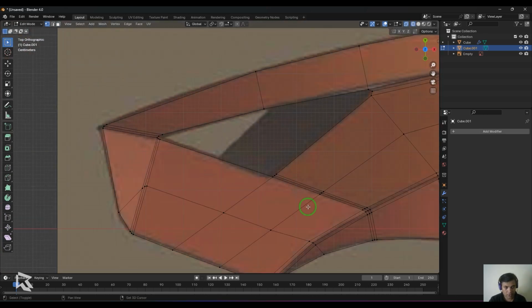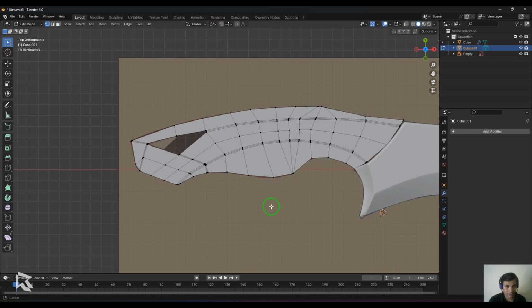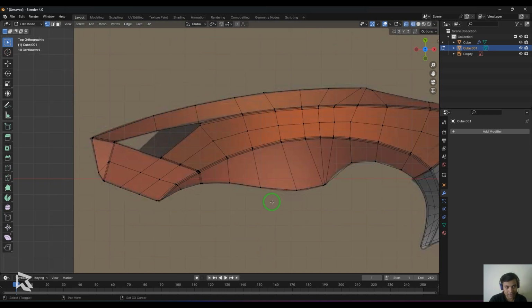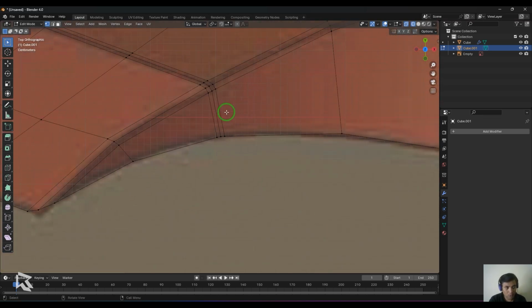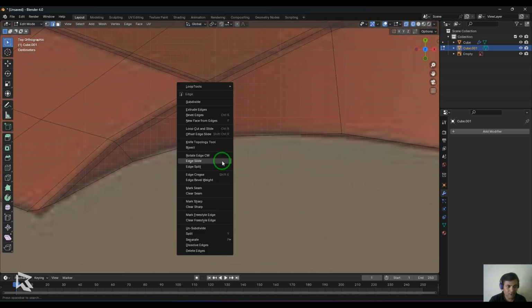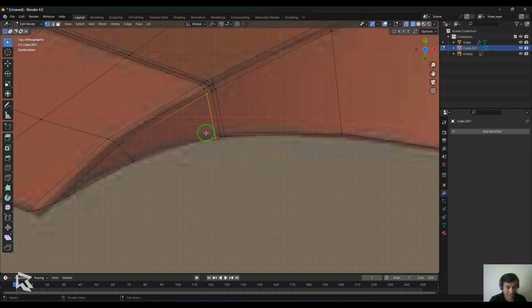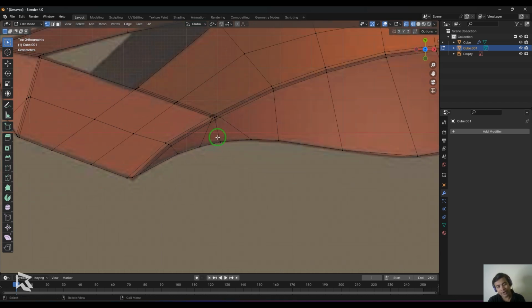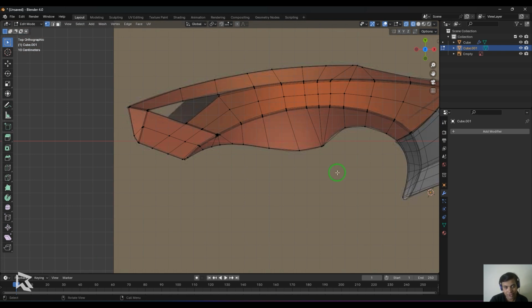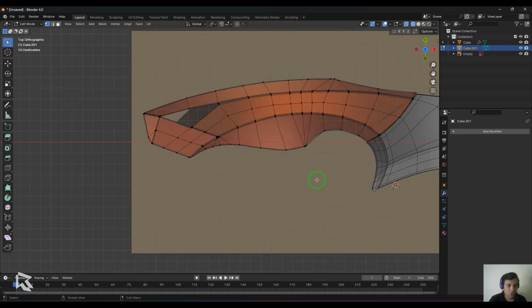Okay, that looks good at this point. So I've got all those lines which I believe to be having those creases. Here I don't want that crease to happen, so I only select one edge or maybe a vertex. Press G and then G. You should be able to see here I'm avoiding that sharp line which generally builds up there. So yeah, good to go.